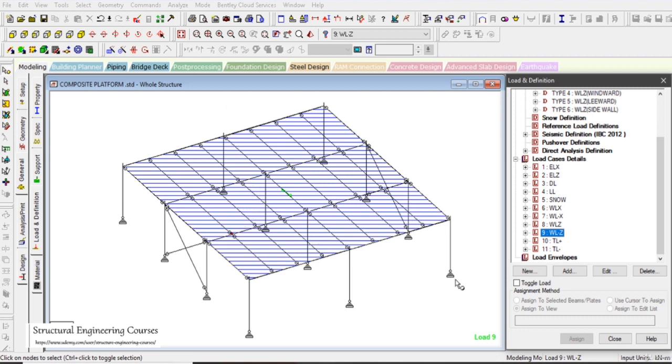But when wind strikes along this x direction, some of the wind component may travel through this part also, but the wind that will act on the sidewall will be very less. So if you talk to me regarding the practical aspects, I shall advise you that you shall only apply wind load along this direction only. There is no need to apply sidewall wind loads here.